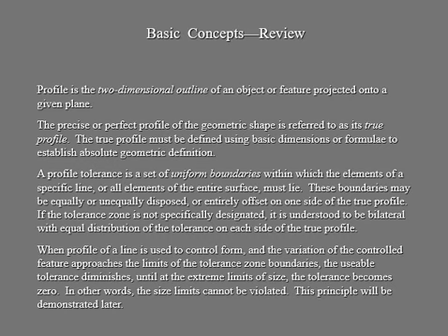Your true profile has got to be defined using only your basic dimensions, to establish your absolute or true geometric definition. And then your profile tolerance has boundaries, and these boundaries are where your lines, your elements, have got to be. Okay, so that's your rule number 1.